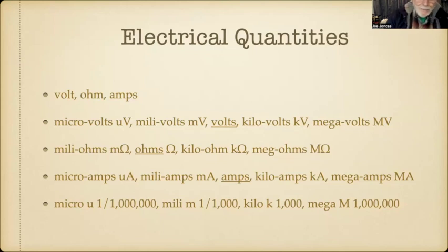And every once in a while you talk about milliohms, and that's if you're trying to measure the resistance of a wire like I showed you earlier. 1,000 milli means 1,000th. And there are megohms. Our meters that we've been showing you have an input resistance of 10 million ohms. We'll be discussing that more later.